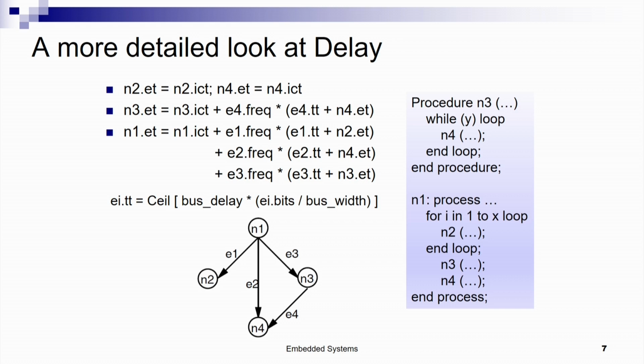As I said, a hardware based implementation could be better in terms of performance, that means lower in terms of overall execution time, but it could be much higher in terms of the cost incurred, so estimation of the execution time is required. One of the important goodness parameters of a partition would be the execution time of the overall application when such a hardware software partition of the modules is obtained.